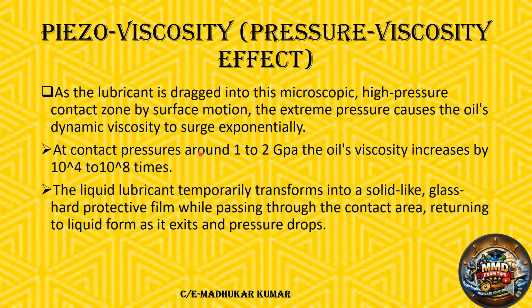At contact pressure around 1 to 2 gigapascal, the oil viscosity increases by 10 to the power 4 to 10 to the power 8 times. This is the thing, and this basically takes the load, and your lubrication also happens. So this is due to the pressure and viscosity effect. In short, it is called the piezo viscosity effect.